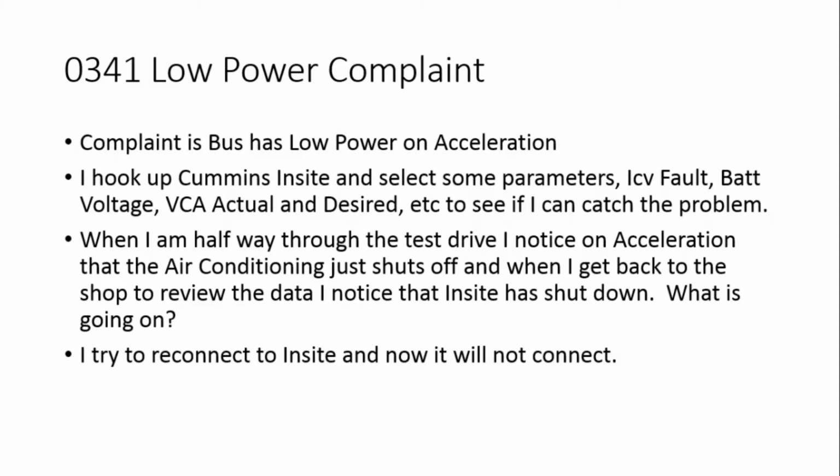So first thing I do with any diagnostic is I hook up and check codes. I hook up the Cummins software and select some parameters to start off on my test drive just to see what's going on. I look at ICV fault, which is injection control valve circuit fault status. I monitor battery voltage, and I'm monitoring VCA actual and desired, which means I'm looking at the valve control angle of the injection pump. I'm doing this because I want to see if there are any issues with these PIDs to help point me in the right direction.